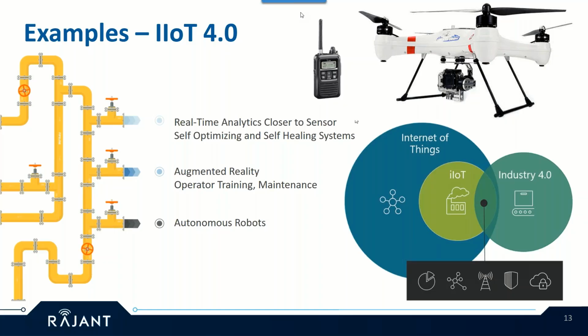There's a lot of things that people are doing with AI in the production field, taking that information to the cloud, looking at performance curves on rod pumps to ensure that the lifting stroke is correct, and bringing all that data back to understand, okay, this pump lifting stroke on this particular formation is occurring at this rate.